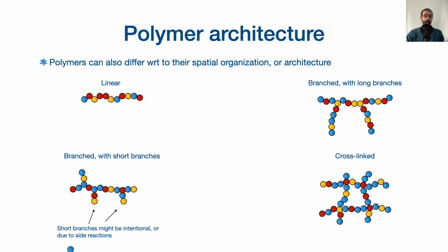Also, their capability of swelling, so increasing the volume of the polymer by soaking up a given liquid, like in diapers, for instance, is affected. So this capability of swelling is affected by cross-links. What else do we have? Well, we have star-shaped polymers, right? And still keep in mind, all of these shapes affect the final polymer properties.